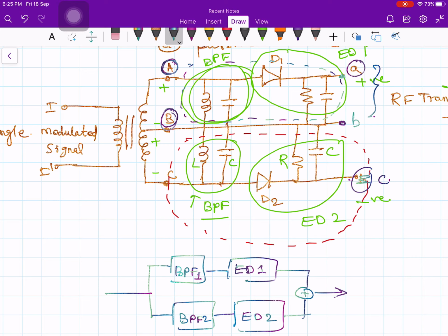If you add the two outputs, effectively you have subtracted, which is what you want to do, because you are adding a positive thing with the corresponding negative thing. Of course, the two envelopes are symmetrical, and you are assuming two envelopes after the band pass filtering.